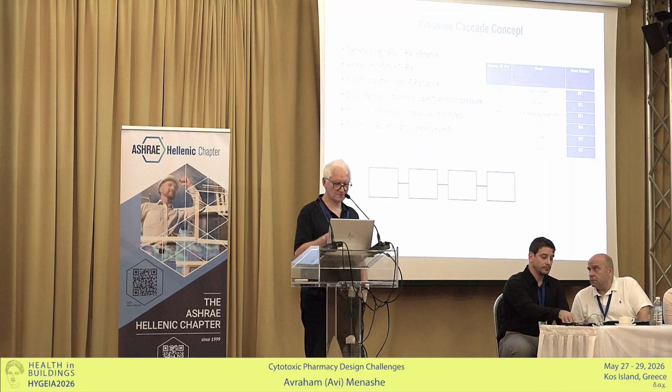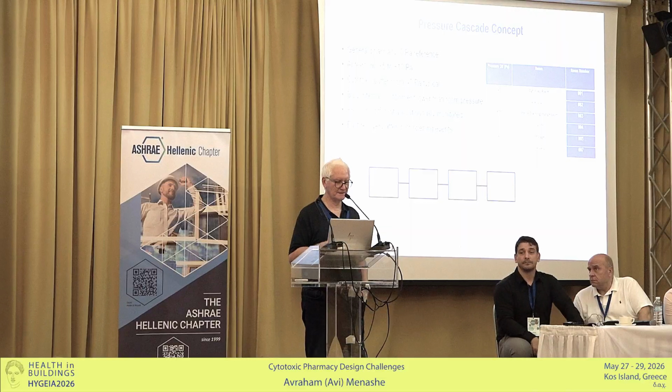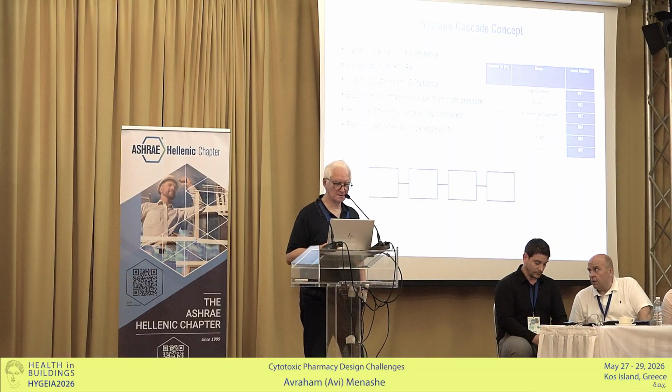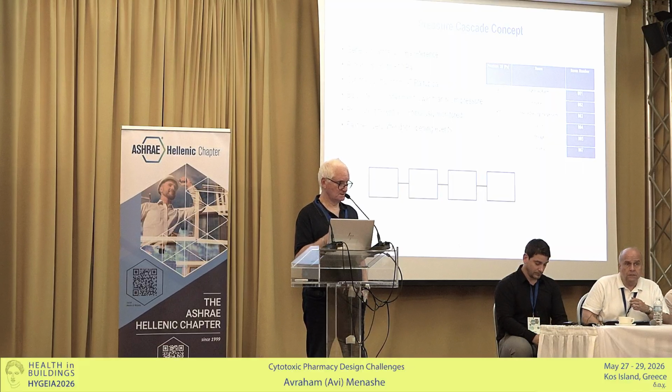The pressure cascade is according to the necessity of the room and the grades. So if you see in the table, there are different levels of pressure according to the rooms that we are taking care of. And this pressure goes from the lowest level, for the highest grade of cleanness, which is about minus 30. Sometimes we are asked to provide a higher level of pressure drop, but it creates a lot of trouble, because if you pay attention, you have the BSL chamber.